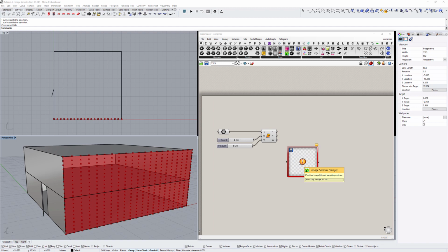Boot up Photoshop. Rather than measuring distance from your attractor point to each of these individual points, what we're going to do now is apply an image onto that surface, and whatever color is in line with that point, it will read that information, and that will translate to a number which we can then translate to a distance or a size or a radius.